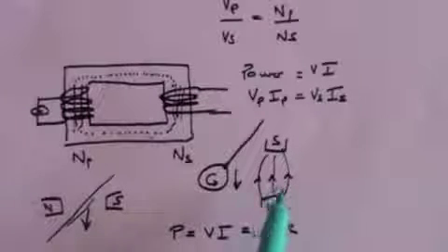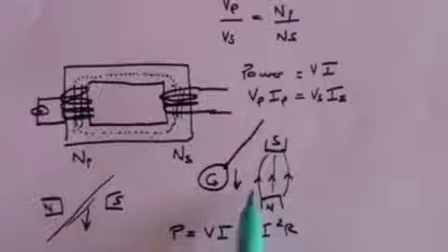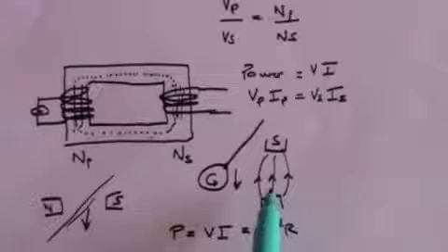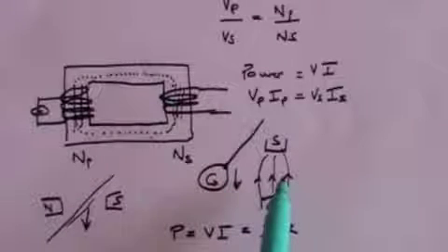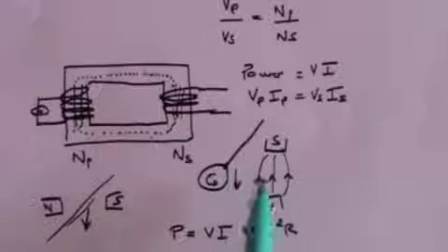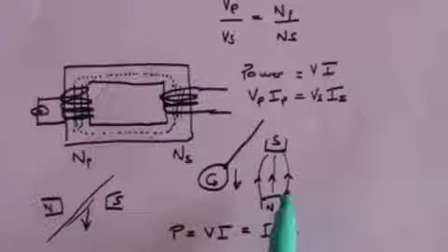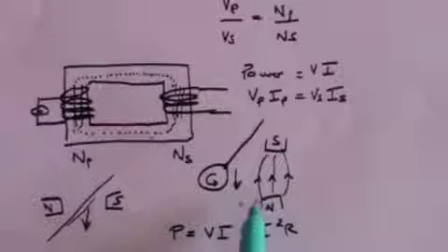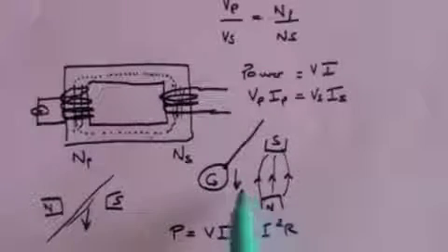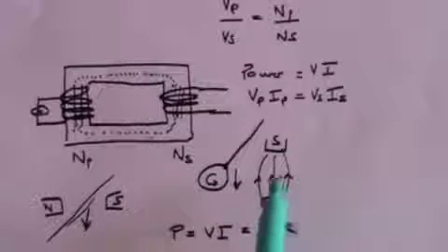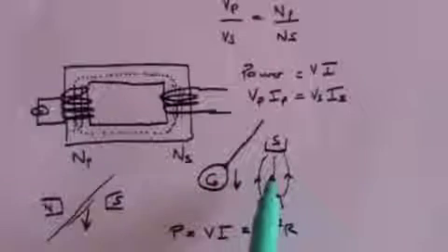And what happens when you lose power? What happens is as the disc goes through, it slows down. It's actually called magnetic braking. This is a way in which braking can be achieved. You have a disc going through a magnetic field. Instead of just swinging backwards and forwards like a pendulum might, it swings and then it goes very, very slowly. It probably doesn't come out. It just stops. It's a braking system. And the reason it brakes is because you've got this eddy current creating a magnetic field in the opposite direction to this magnetic field, generating heat and losing power, and the whole thing brakes this pendulum.